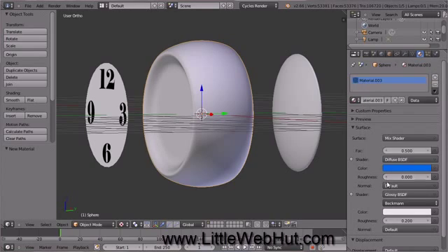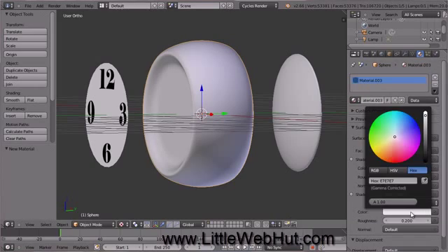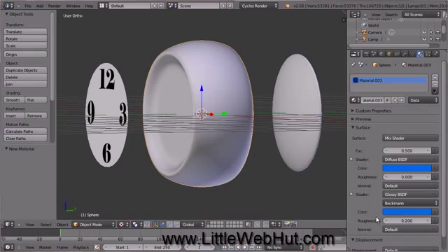Now do the same thing for the second shader. Click in the white area, make sure the hex button is selected, and enter 0068E7 and press the enter key. Now below the color button there is an entry box called Roughness. Set this to a value of 0, which will give the surface more shine. The value in this entry box specifies the proportions of the two materials that we are using. Set this value to 0.2.